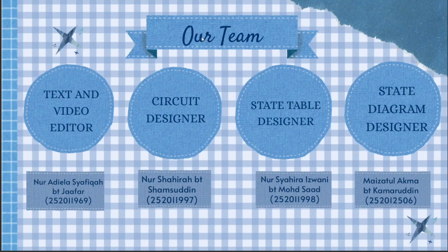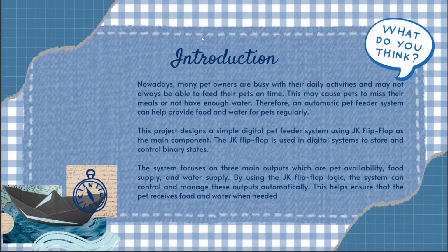The purpose of this project is to design a digital control system for an automatic pet feeder using a sequential logic circuit. In this design, we use JK flip-flops as the primary control element to manage three variables, which are pet availability, food level, and water level. Unlike simple combinational logic, this sequential circuit maintains a stable feeding or hydrating state, which prevents mechanical dispensers from chattering due to minor sensor fluctuation.